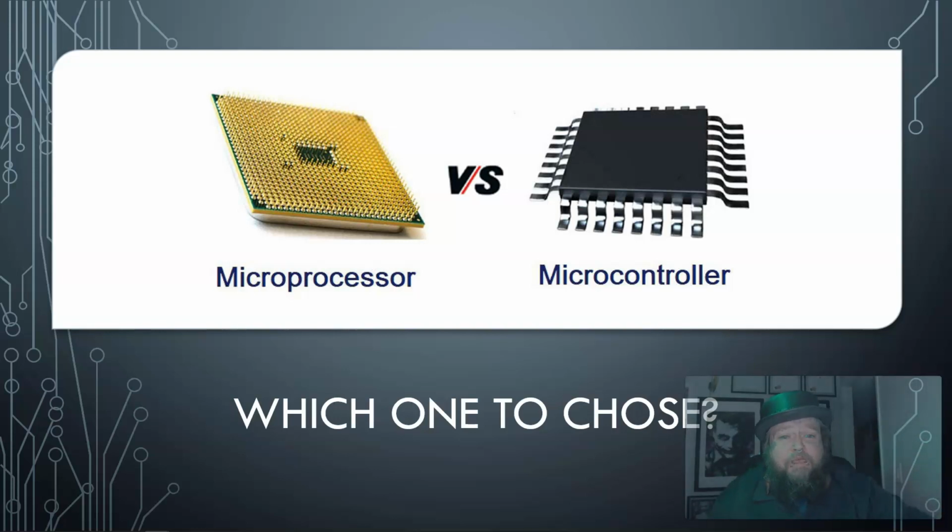Now, in the beginning here, you could go with either. If you're working with basic projects like turning on an LED to flash, you can do it with both. It's not a very big thing, but I prefer to work with microcontrollers in this case, because with a microprocessor, you almost have to set it up like a separate computer. You have to hook up your own monitor to it, some kind of keyboard to do your work, or you have to connect it to your network and remotely connect to it. If you've got those skills, that's fine, but not everyone coming to this course does, or is it really feasible to always keep doing that? Whereas with microcontrollers, you just need your one computer, you plug it in, you install whatever software it needs to communicate with it, you do your computer programming, compile it and transfer it to that device.